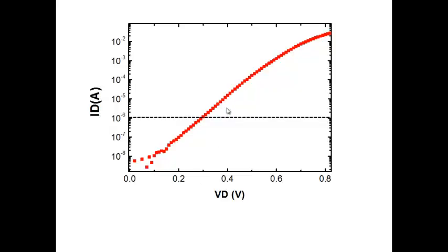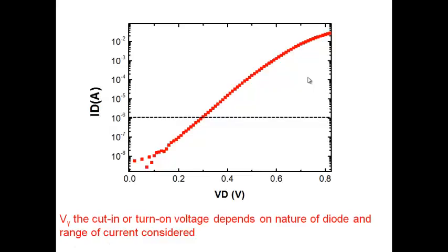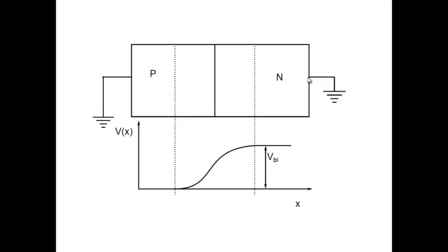And depending on that range of current, you approximate the diode by 0.6 or 0.5 or 0.4 or 0.3. There is no cut-in voltage inside the diode here. Okay? So keep that in mind. Now the other misconception that arises, once you think that there is some unique cut-in voltage inside a diode. Suppose you do carry the impression that there is a cut-in voltage inside a diode.